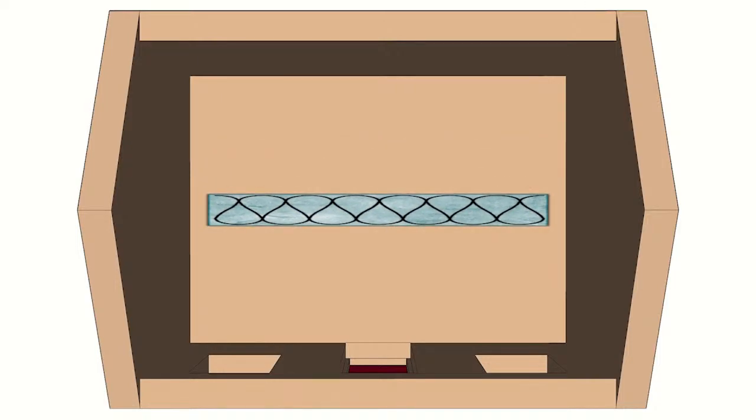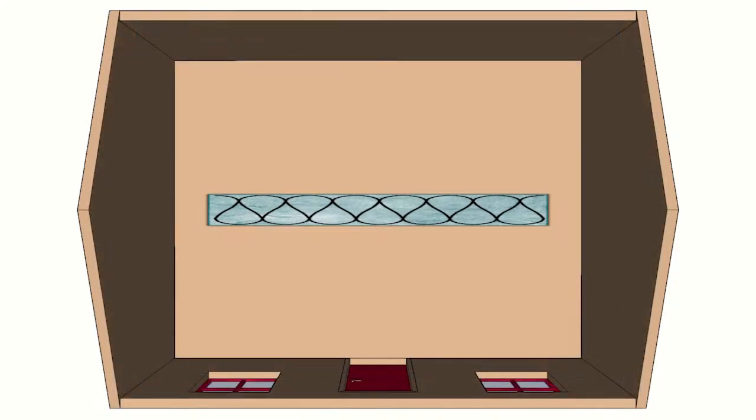Aerogel composites such as our Spacetherm, on the other hand, can maintain permeability whilst reducing the required depth dramatically. This makes it ideal for use in rooms with limited floor area, as well as at door and window reveals and other areas where retaining existing features limits the use of thick and bulky insulation.